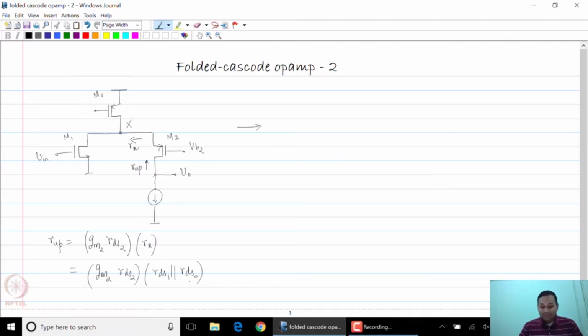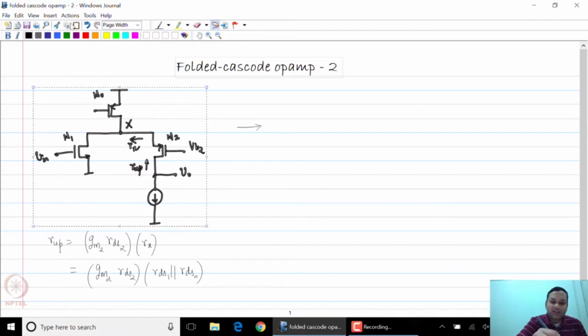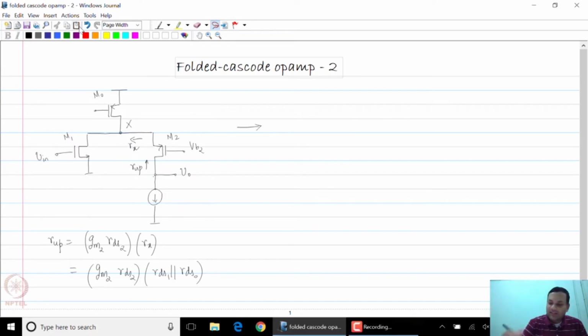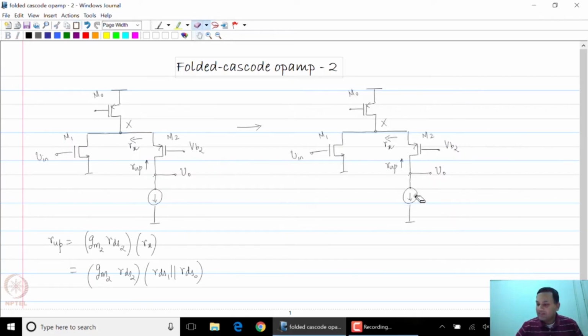So this is of course quite high. We now want to use an ideal current source here, but we know we can't do that. So let us first try to replace that with a transistor, with an NMOS transistor, because this is a current flowing downwards. The first thing we'll try to do is to replace it with some VB at its gate such that this has some current.